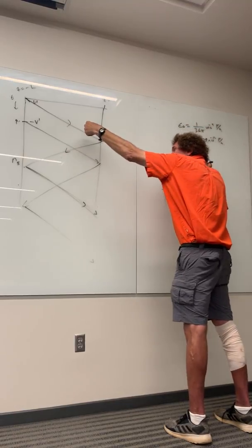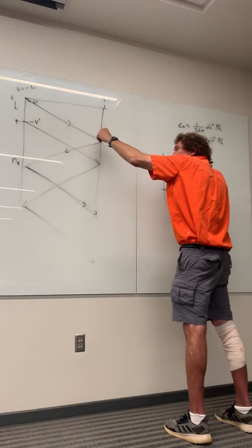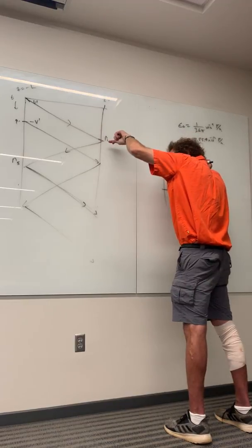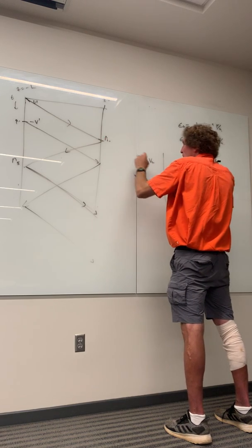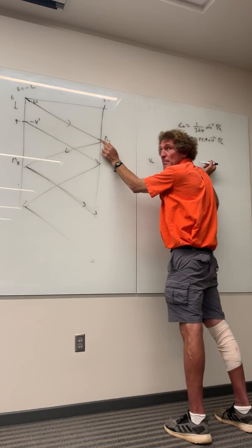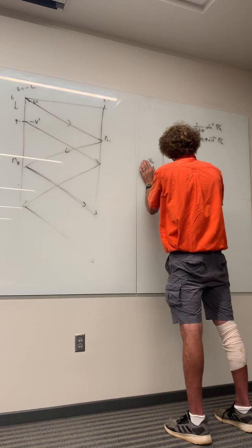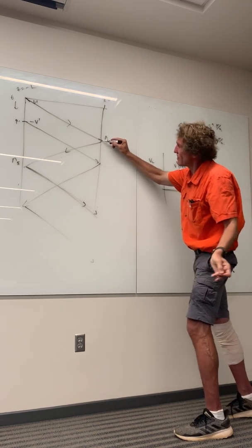Because V prime gamma L is going that way, V prime hits, but V prime gamma L is going that way, and they're superimposed at that point. So then I get V prime times 1 plus gamma L right here, and it stays there for how long?